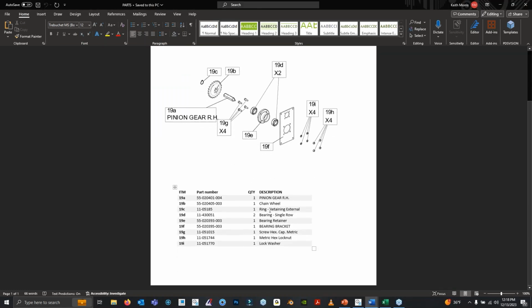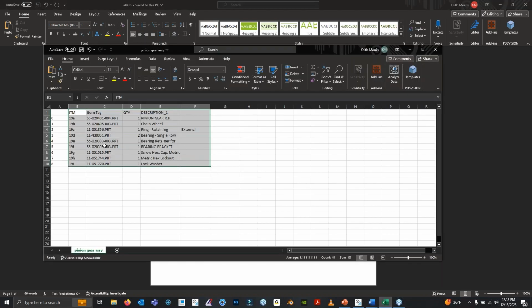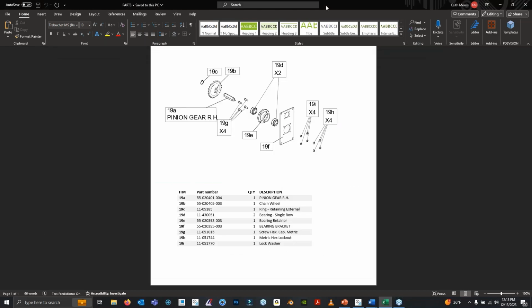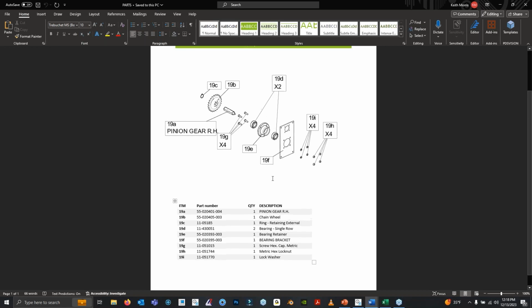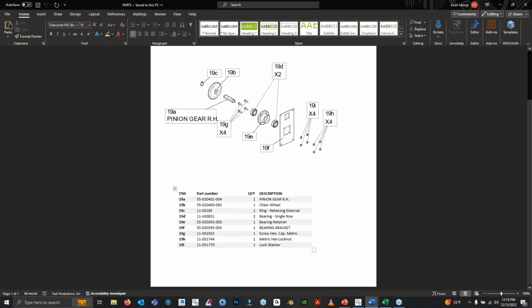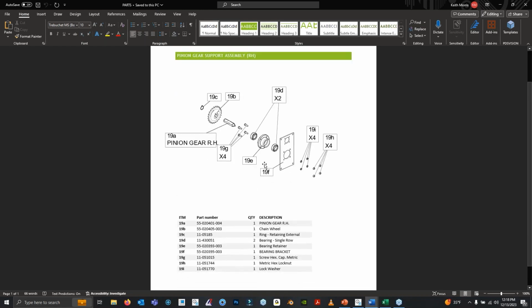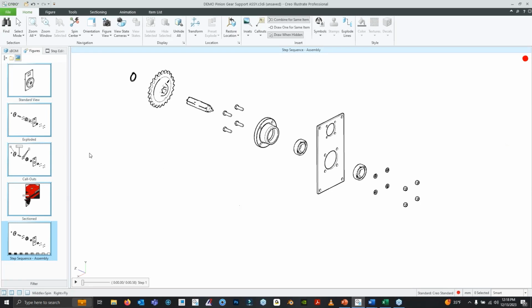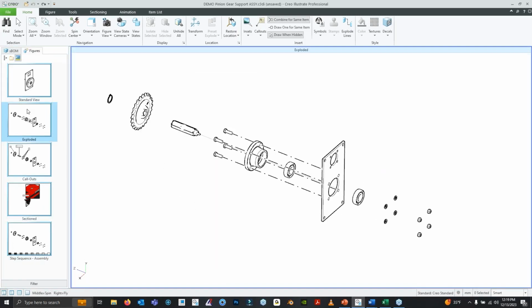I won't go into detail about this, but basically this list was from an exported CSV file, which I have here. So this is literally what came from Illustrate. It can export CSV files of your item list. And all I did was copy this over to the document, and then I highlighted everything and basically converted it to a table. I had to finagle it a little bit, but usually this is what we see on any given page of that sort of documentation. So that's how you get these images set up, rendered, and published out.